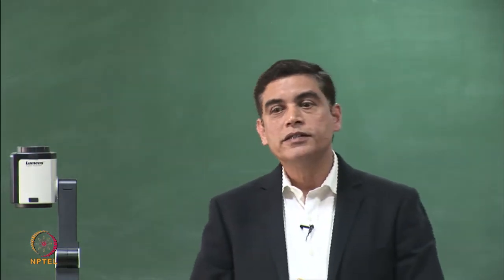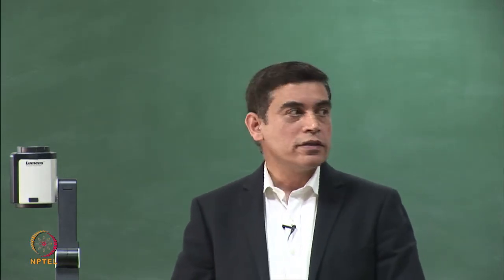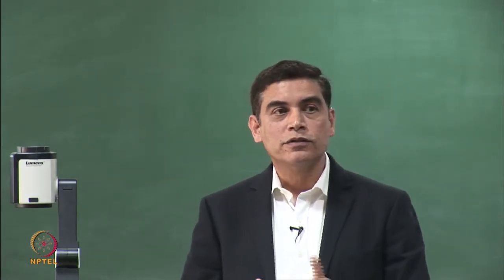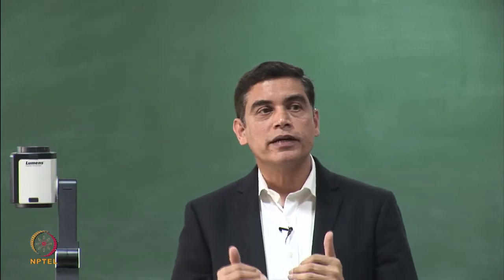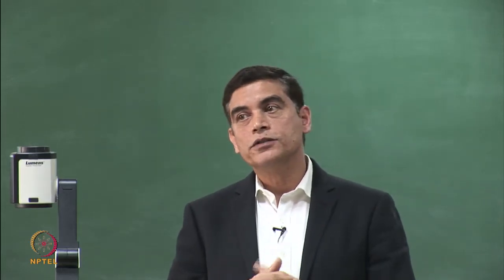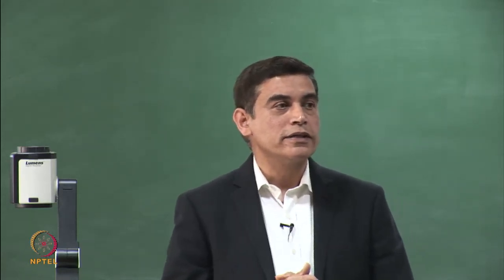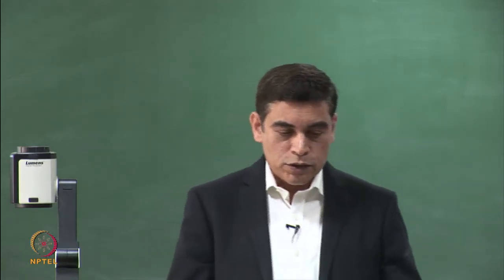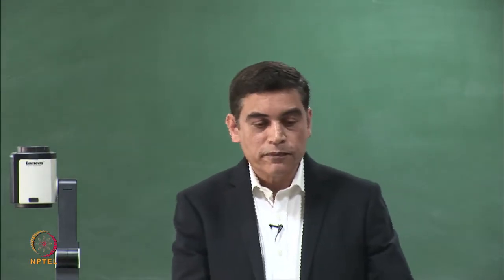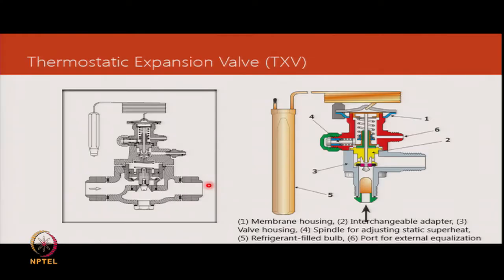would need such a device when you want a constant evaporating temperature, because at saturation these two are related. So, if you are targeting a constant evaporating temperature, you would do this. This is not the most commonly used expansion device. So, now what we are going to get to next is a thermostatic expansion valve.